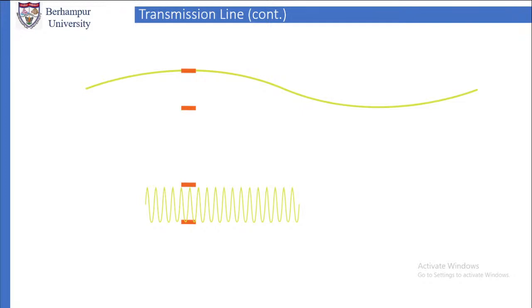A resistive device is basically a resistor or a resistance or a conductance. Reactive devices are capacitance and inductances. So a combination R plus jX is impedance. R is resistance, X is reactance. X can be equal to omega L, or 1 upon omega C. If it is inductance, it will be omega L. If it is capacitance, it will be 1 upon omega C. So that is what an impedance is.